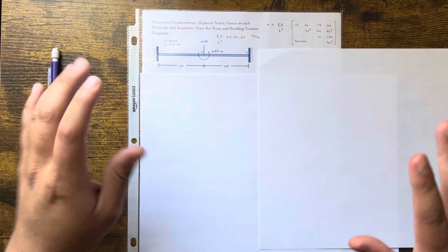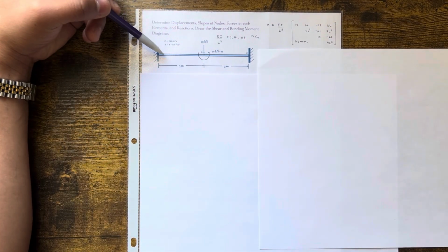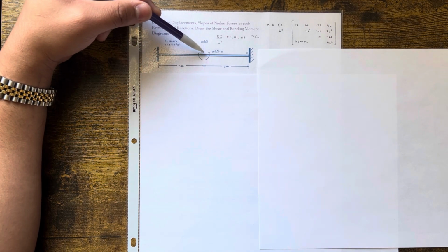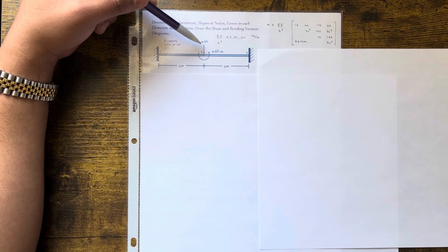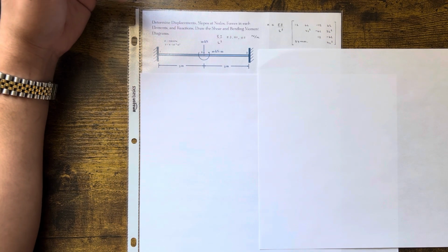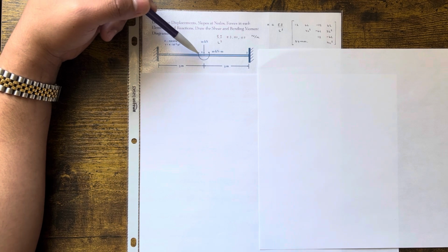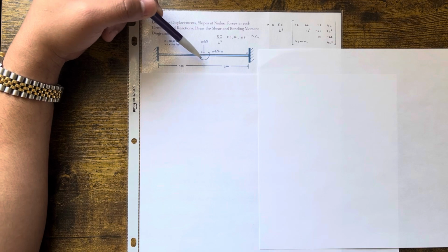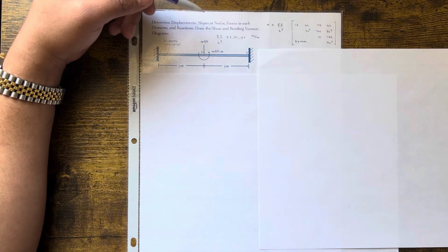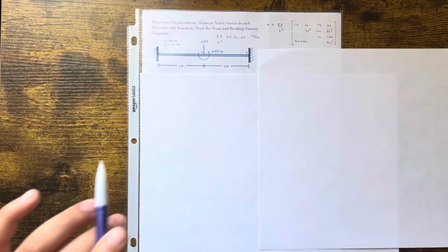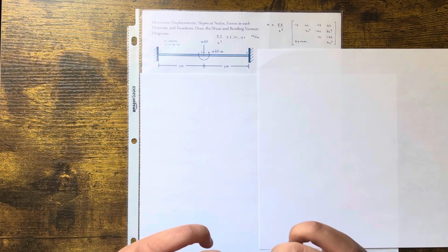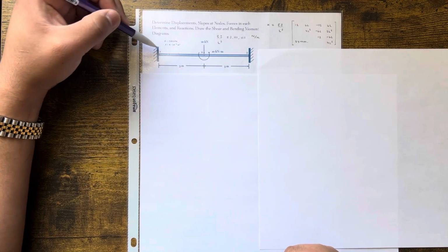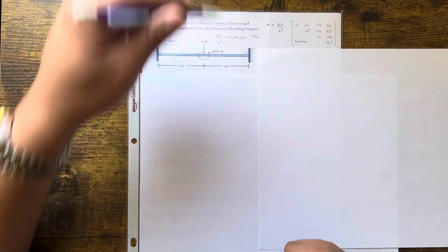All right, so in this case, we got two elements, right? Element number 1 between nodes 1 and 2, and element number 2 between nodes 2 and 3. At node 2, you have a downward force of 20 kilonewtons. At node 2, you also have a twist happening right at the center, right? Pretend like a beam is coming out and it's causing something to twist. It could be anything, right? But I'm just trying to give you guys an insight as to what's happening here. It could be a design problem, right? You have a force and a moment at that node. Nothing going on at 1, nothing going on at 3.